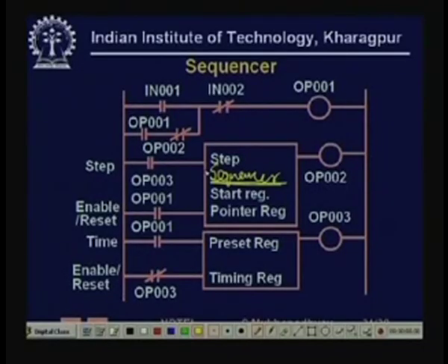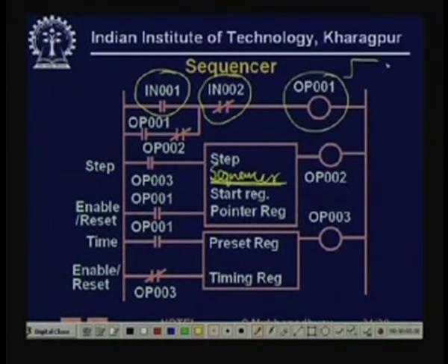First of all, this is the master switch which will become on. Let us assume that this is off. First of all, what happens is that this goes high. When this goes high and this is already low, there is a path from this place to this place, and even if this is taken off, this path maintains.